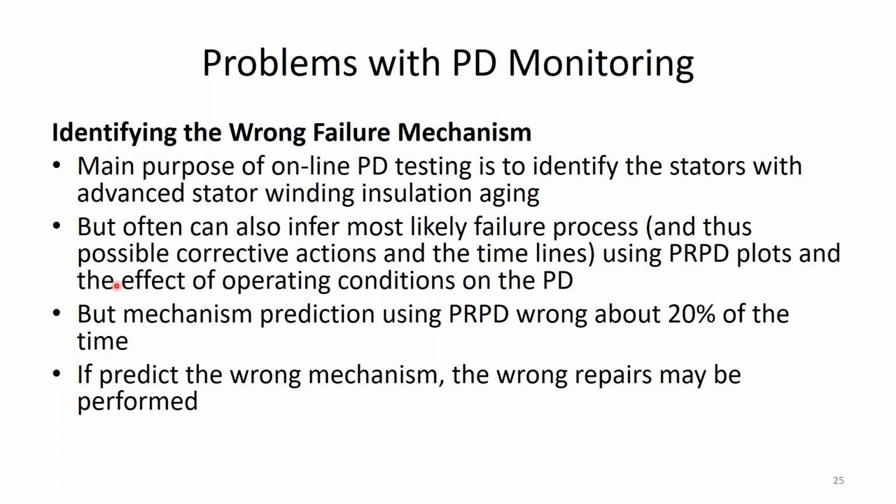It doesn't necessarily always show a positive predominance. It might not always be in the part of the AC cycle where you expect it. It might not have that nice special triangle pattern that we often associate with PRPD patterns. And again, we've learned this the hard way, because we've sometimes given incorrect information to customers purely by looking at those PRPD patterns, and we've found that they're sometimes wrong. So don't go overboard with those things.